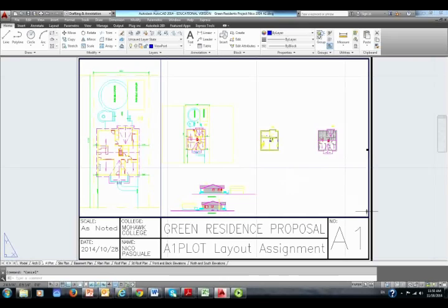So now within this viewport, how about dividing it into two equal spaces and having site plan and elevations? Or another thing, maybe I'll copy this and see if it will fit that plan. In larger scale, no, it won't. No, so I'm going to go with plan 1. I'm going to draw a line in paper space from here to here, enter, and then enter again for another line and look for midpoint.